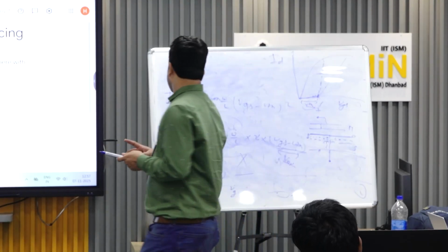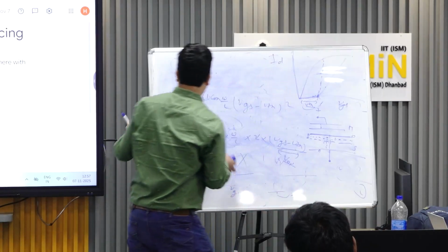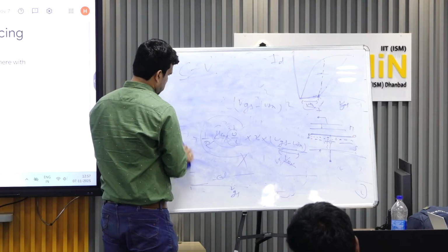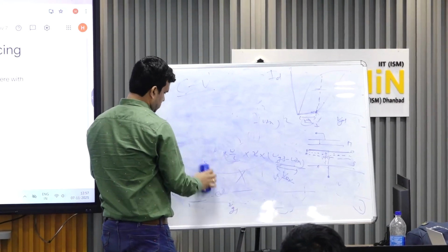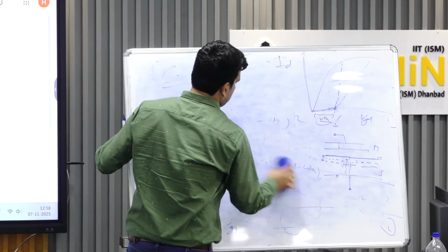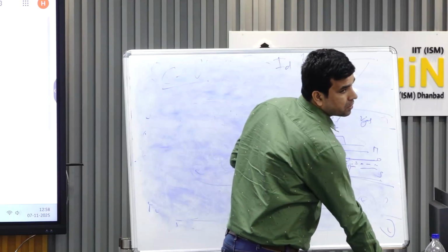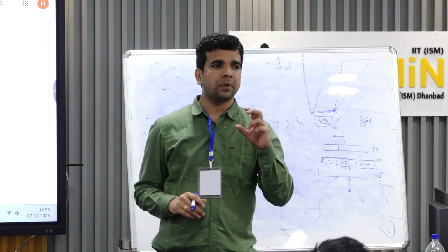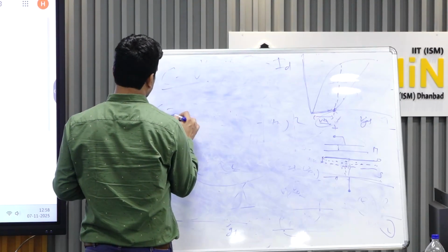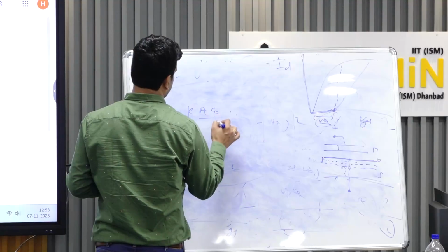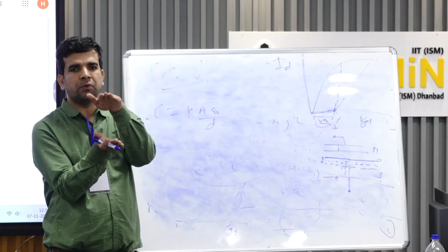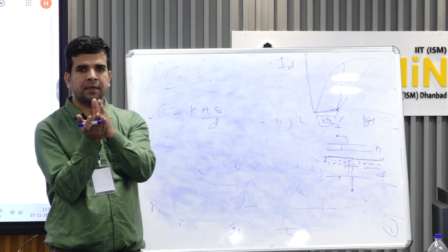Okay. Then sometimes CV measurement will help you find defects, traps, and other things also. Since you know the capacitance C equals K A epsilon naught by D, right? If you have your oxide thickness, whatever gate oxide you have, you have certain trap states, certain ions and other things.